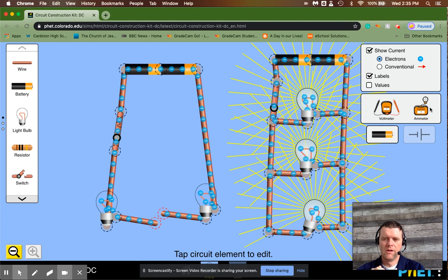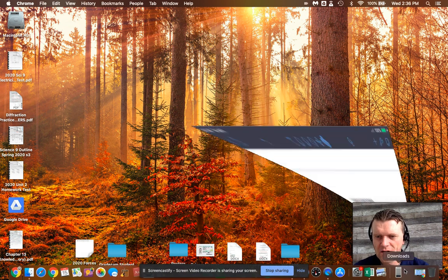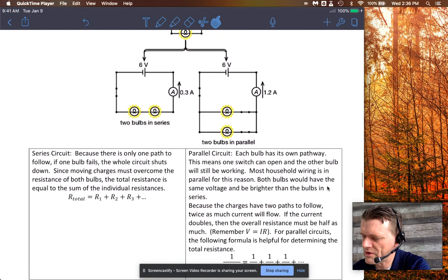But in terms of the voltage, that's what makes parallel circuits so fun: the voltage is the same across each branch. So if you're doomed to have the Christmas lights that are set up in series, then if one of the light bulbs burns out, the whole strand goes out. And you're like, honestly, where is it? That's really annoying. But most newer Christmas lights are done in some form of parallel circuit, so that if one light bulb goes out, the whole thing doesn't go out, and then you can easily find the one that's burned out and replace it. But anyway, I'll let you guys play with that when you get some time, because it helps you understand the basics of circuits.